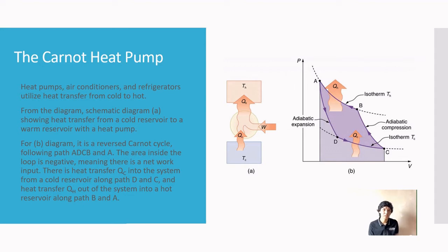It says backward rather than reverse because except for Carnot engines, all heat engines, though they can be run backward, cannot truly be reversed. Heat transfer occurs from the cold reservoir, which is QC, into a hot one. This requires work input, which is W, which is also converted to heat transfer. Thus, the heat transfer to the hot reservoir is QH equal to QC plus W.